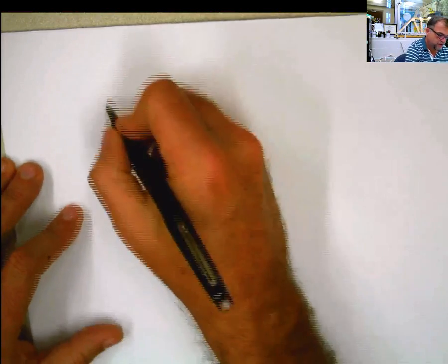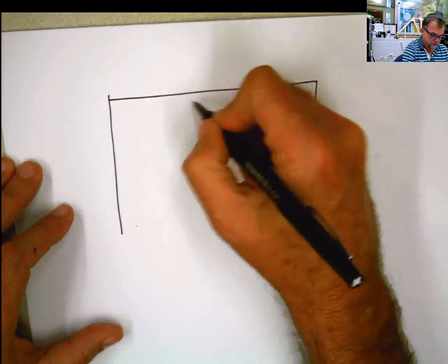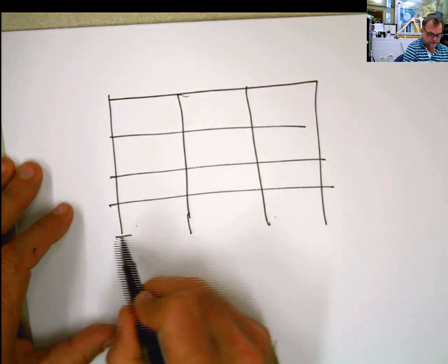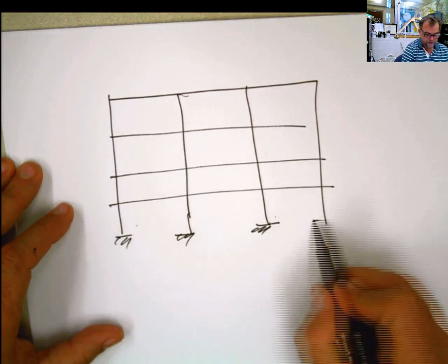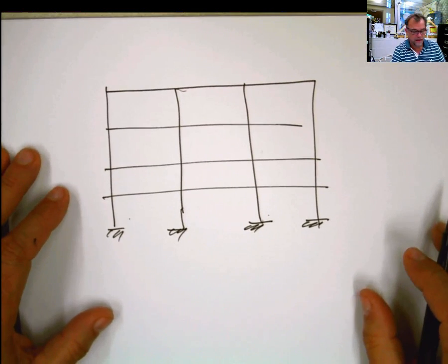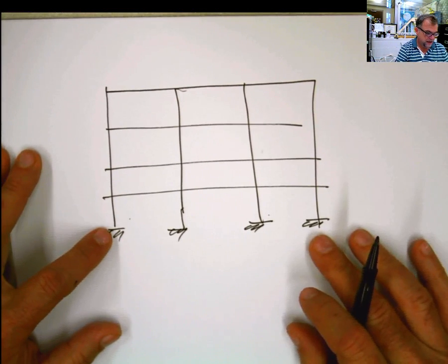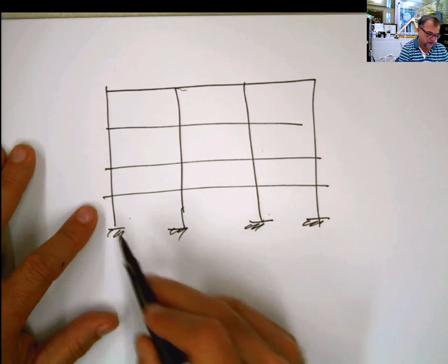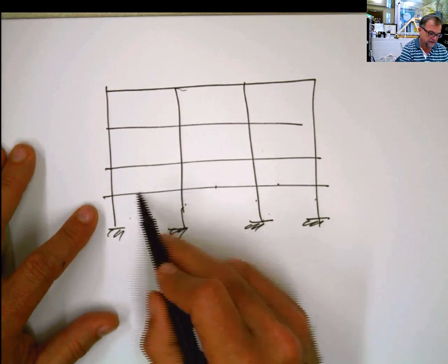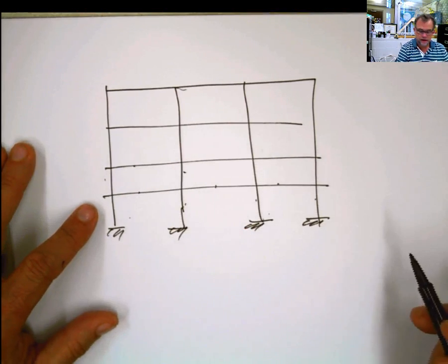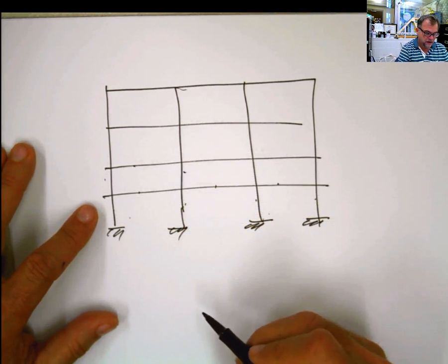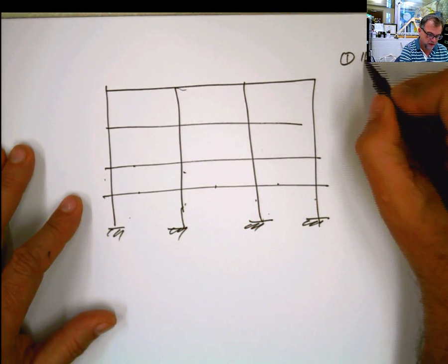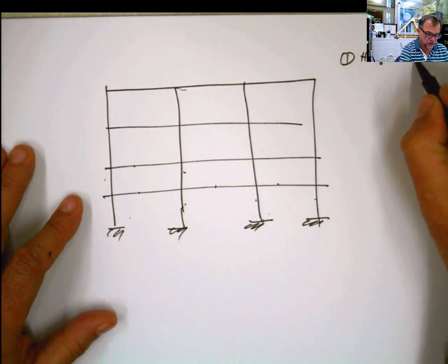Forget about this now. Imagine that you have something like that, and you have to start by solving this. Well, hinges everywhere. That's what you have to do. You put hinges, hinges, hinges everywhere. Every single half length, you have to put a hinge. And now how do you solve that? Well, there is a second assumption. The first assumption is you have to place hinges at inflection points.